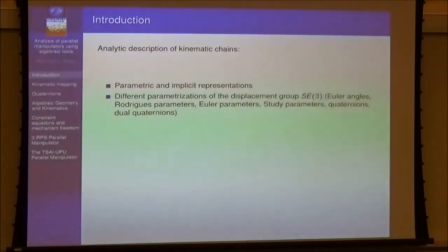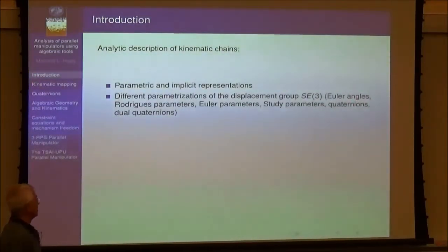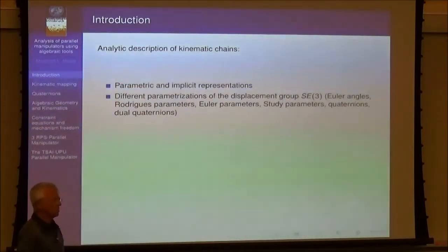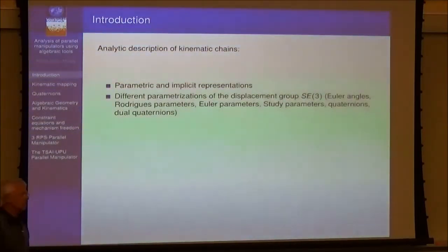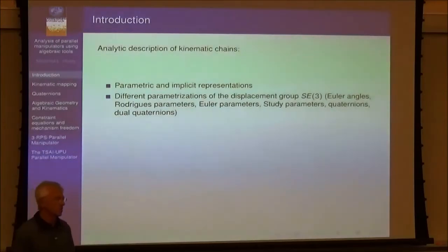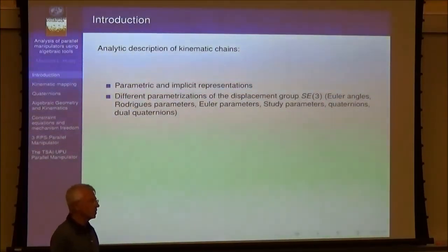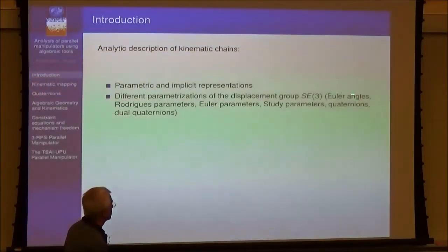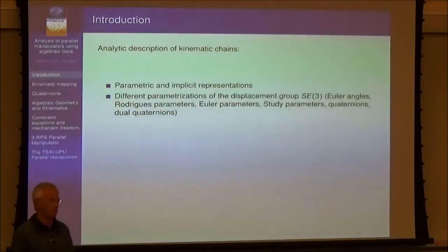Euler angles, for example, have a disadvantage. They do not cover all rotations in free space. The reason is, sometimes students are asking me, what, Euler angles are not representing everything? Then I tell my students, okay, I give you a lower dimensional example of what parametrization singularity means.